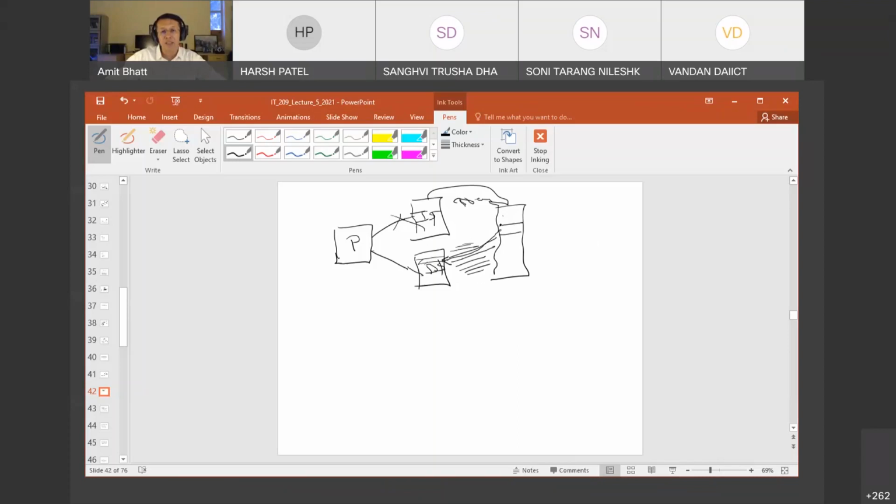You don't have to do it. The manufacturers do it. Now there are 64 lines and each word is 32-bit. Then only 2 words can go in parallel. Now I have got, say, a 16-word block. Then I have to spend 8 cycles.